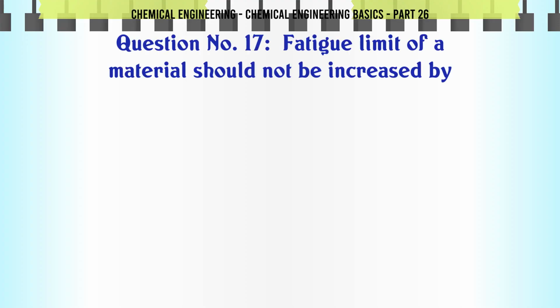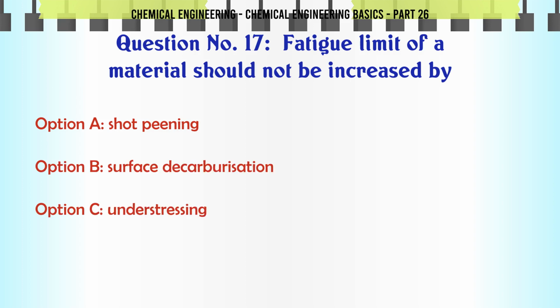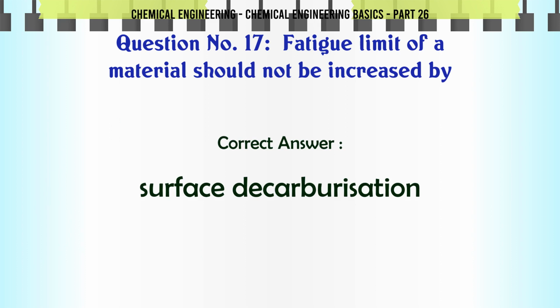Fatigue limit of a material should not be increased by A. Shot peening, B. Surface decarburization, C. Understressing, D. Cold working. The correct answer is surface decarburization.